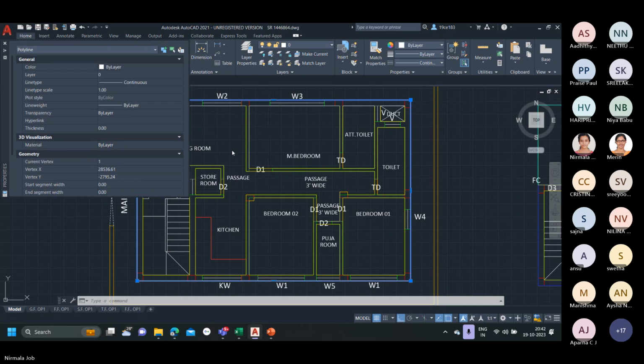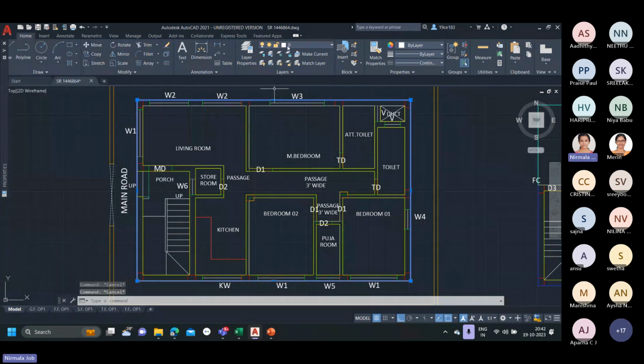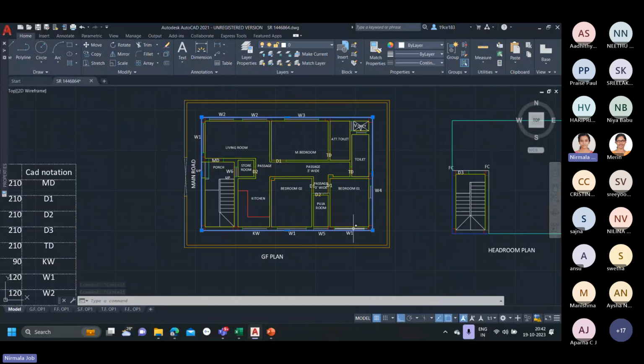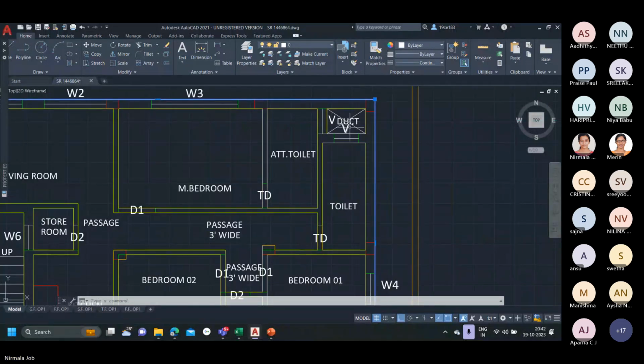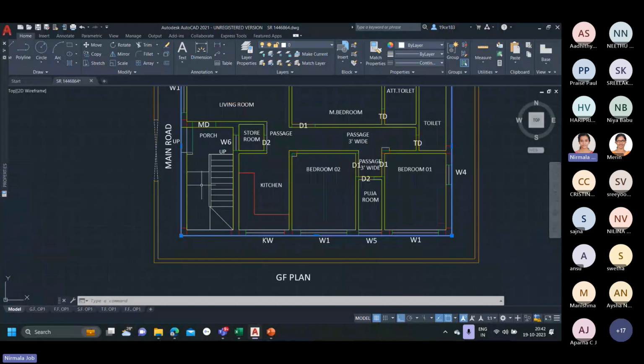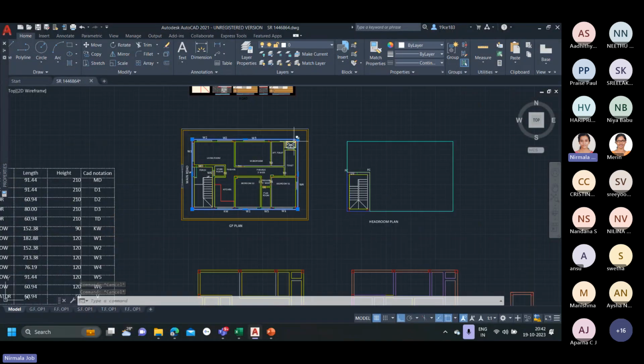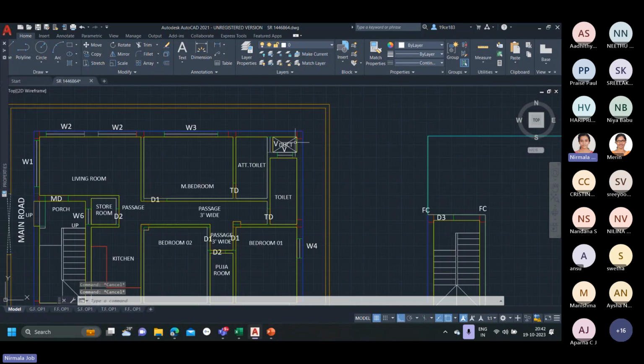And this specific zero layer line is known as the slab of this particular floor level. And if I have certain notations like duct and stair area, we need to deduct the slab at those areas as well. So after drawing the slab area over the entire slab section, we need to provide the slab deductions too.